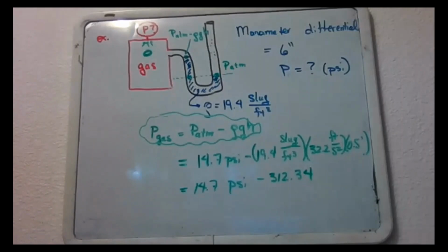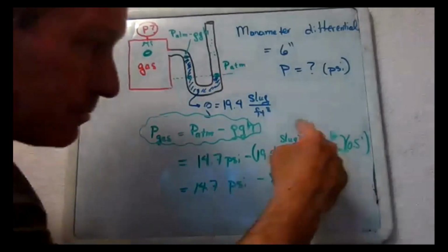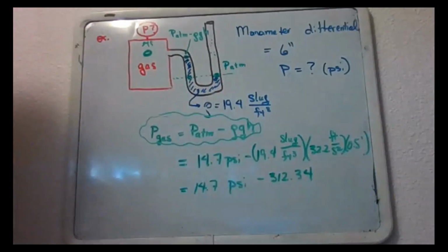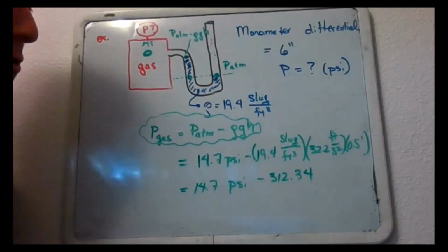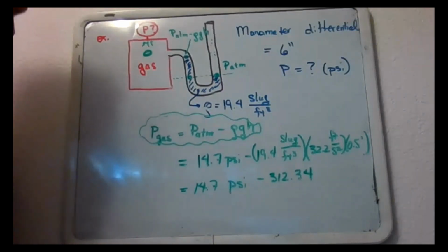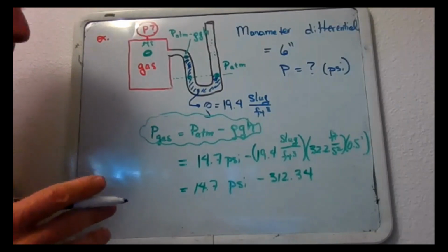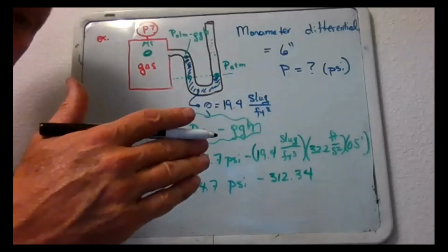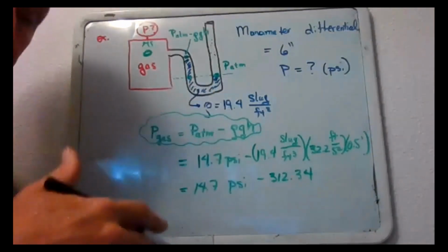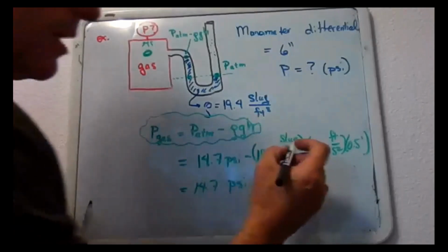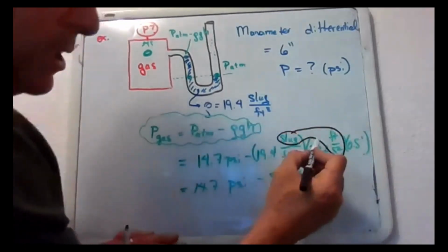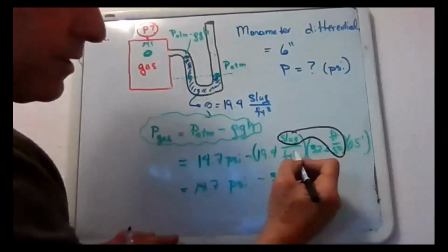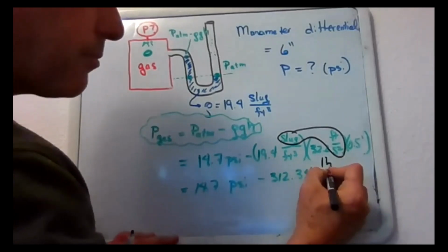Okay, so as someone was asking last time, how about dealing with all this mess of units? There is a table in the back of the book that you can use to do conversions. That's okay with me, but I really hope you can work this summer on going back and forth between units like pressure units, pound units, and units with slugs. A key thing to remember is that a slug foot per second squared is a pound. So that's a pound, this is a foot, that's a foot cubed. All this is a pound per foot squared.